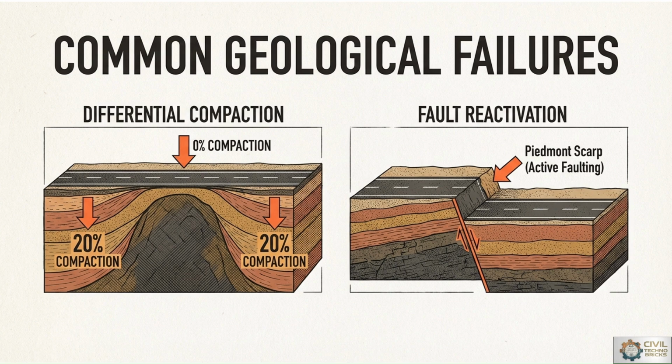So what are the common geological failures? Highway construction often requires excavation through soil and rock formations. Geological conditions determine excavation methods and slope support requirements. They may be based on the fault plane, fold plane, dip and strike. Rock cuttings in fractured formations may lead to rockfalls and instability.